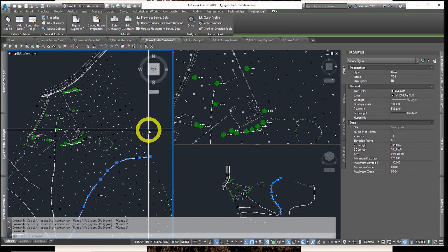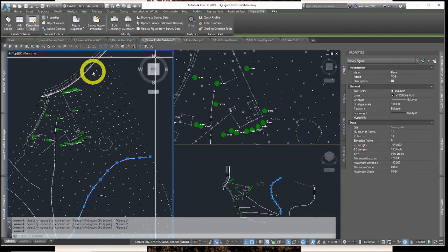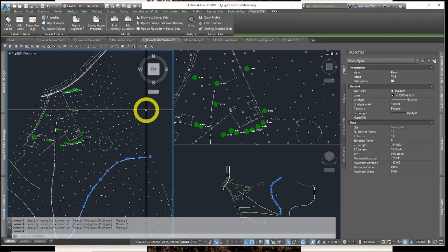They have special characteristics that allow them to be edited certain ways in Civil 3D up here, and they're very much like feature lines, which we'll later encounter, and this is part of learning Civil 3D with 2D and 3D properties and various ways to edit them. But survey figures are specific to survey data. They get linked in the survey database with survey points. So that being said, we're going to move to page 52 and talk about point groups.